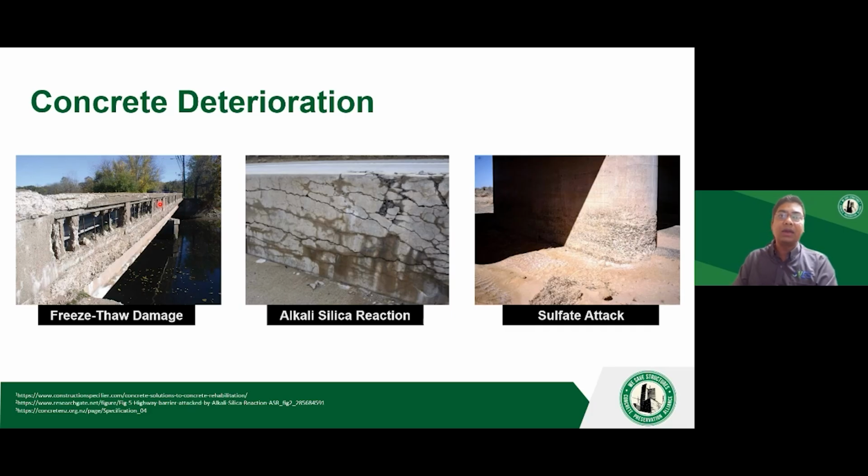So that's alkali-silica reaction. In parking structures which are exposed, like underground parking structures exposed to acidic soils, you can have something called a sulfate attack, where the sulfates in the soil can attack the cement paste and eat away the cement paste, thereby making sure that the concrete is cracked or the cover depths are reduced.